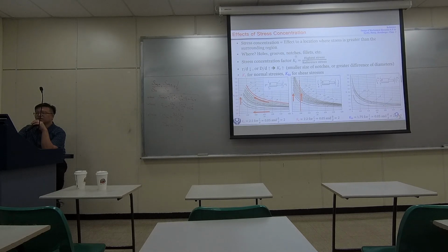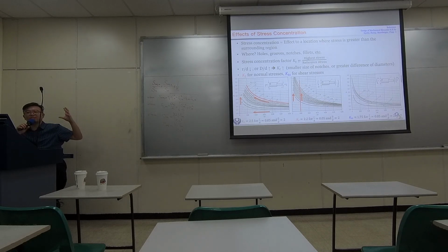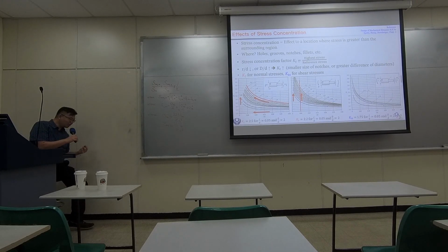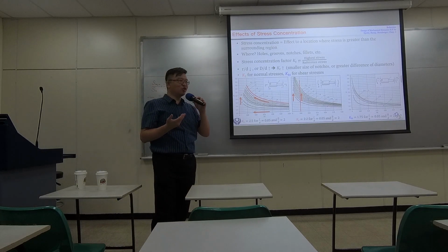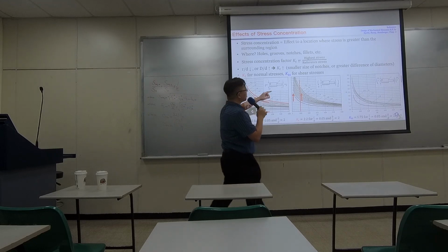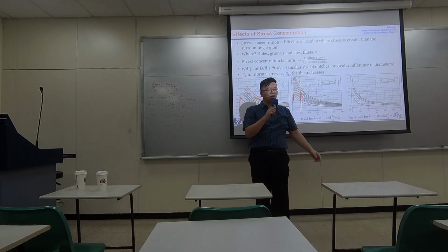We usually use the symbol K. So K equals, in a mechanical part carrying some kind of load, if we don't talk about stress concentration, you can use mechanics of materials to compute the stress value that we usually know. We call those values the reference stress.